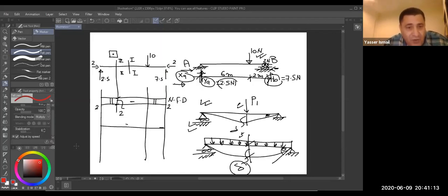So we have a force here. This is the first force on my left hand side. This force is pointing up, so up 2.5, straight until the force giving me 10 down. This is 2.5 until it goes down, so here it is 7.5. Straight until the reaction of 7.5 goes up, giving 0.